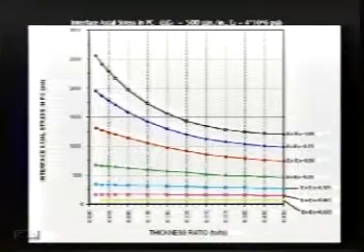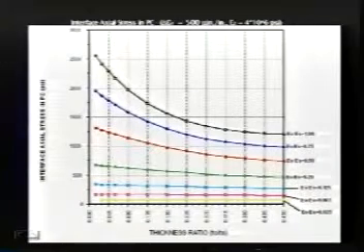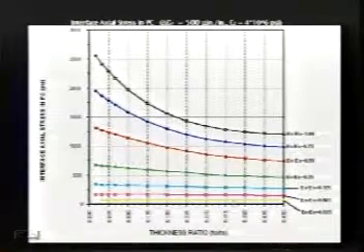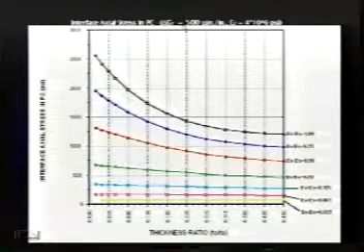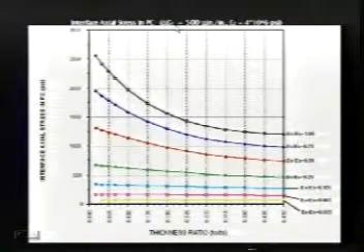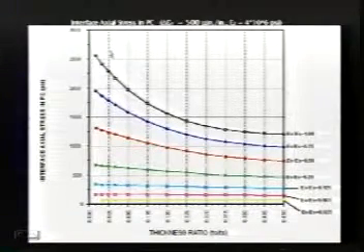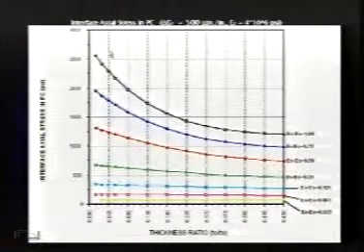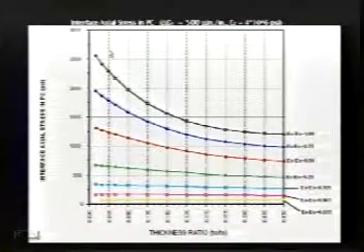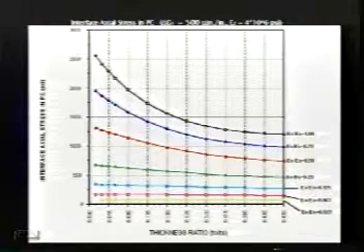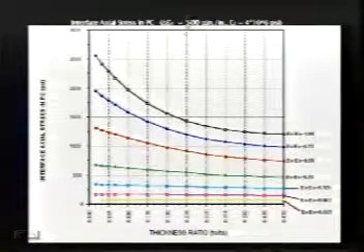What we reduced all of this down to was a set of curves. This could all be done on the computer, but it can also be done by hand. This shows the interface axial stresses. We had to select a value of strain that we could use to produce this. And this value of strain represents the temperature change times the difference in coefficient of thermal expansion between the concrete and the polymer concrete. So that's pretty simple. We set that at 500.